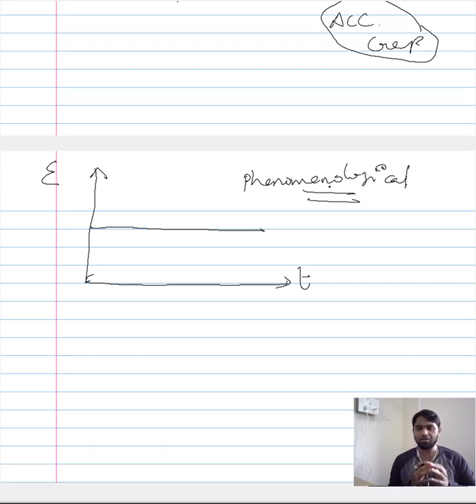And whenever people refer to the phenomenology of creep, this is what they mean. Instead of considering the whole creep curve, they section it. They understand the theoretical reason for each of these sections, because each section has a characteristic property. Take the steady state region, wherein the slope is constant: there is a theoretical reason for this constant slope in creep behavior, and I can then understand what the reason for it is.